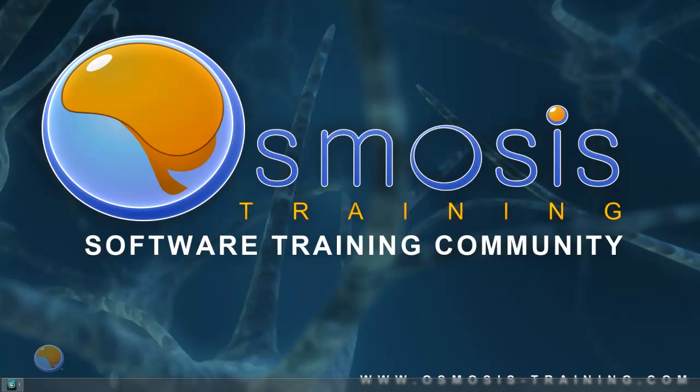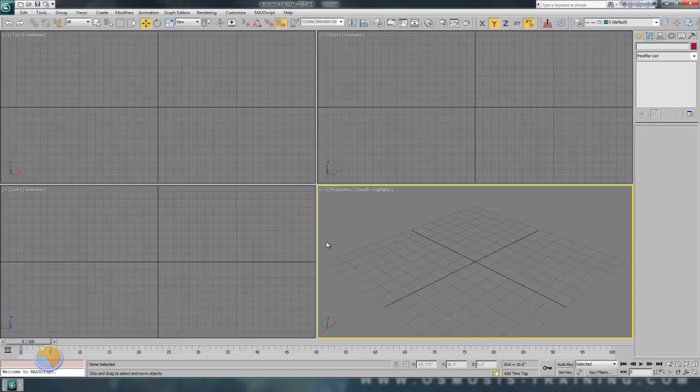So let me go ahead and jump right in. Today's basic animation. In this tutorial we're going to set up some basic keyframes and do a real simple animation, an introductory session on how to create simple animation, and I'll even show you some different types of tangents for your keyframes. We're going to just be using the simple auto key feature in 3D Studio Max, and by the end of this lesson you should be able to do some simple animation using Max.